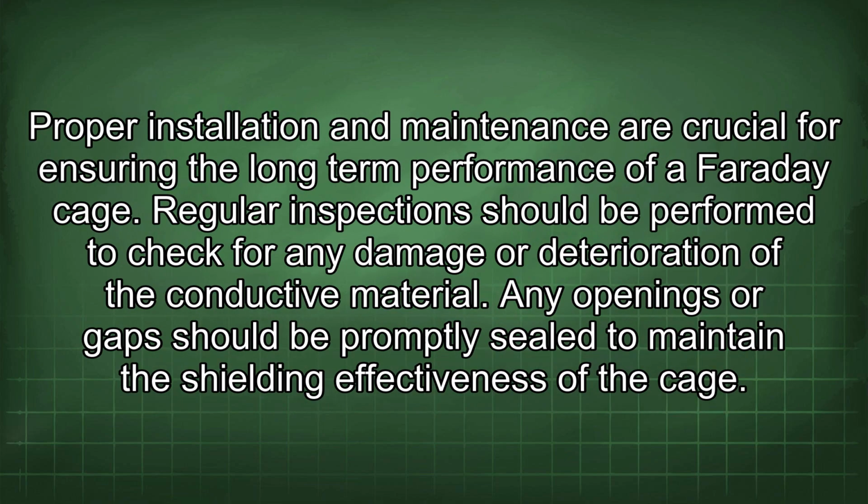Proper installation and maintenance are crucial for ensuring the long-term performance of a Faraday cage. Regular inspections should be performed to check for any damage or deterioration of the conductive material. Any openings or gaps should be promptly sealed to maintain the shielding effectiveness of the cage.